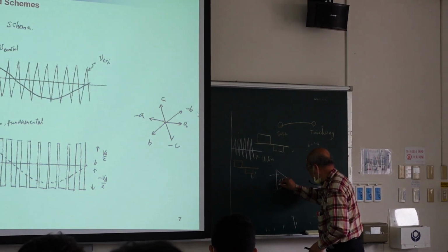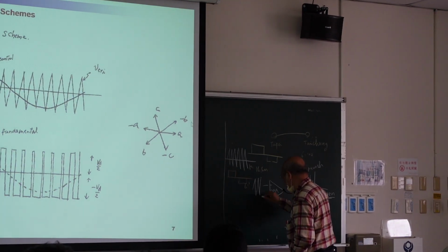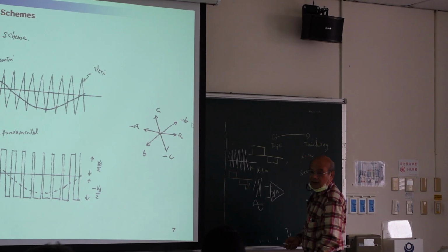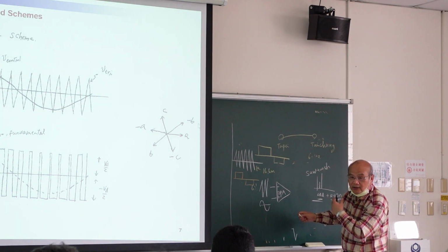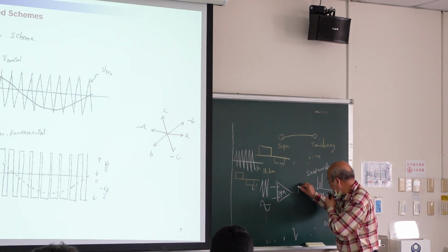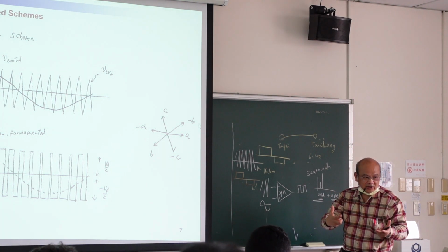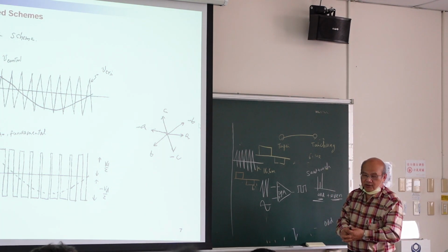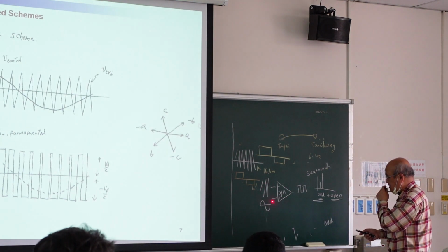And we have two signals. One is the carrier, another is sinusoidal. And we use the voltage comparison, and then we can generate a high or low signal, right? Then we can get the triggering signal. So we use an operational amplifier to do the comparison.